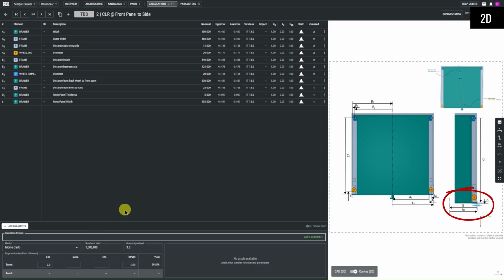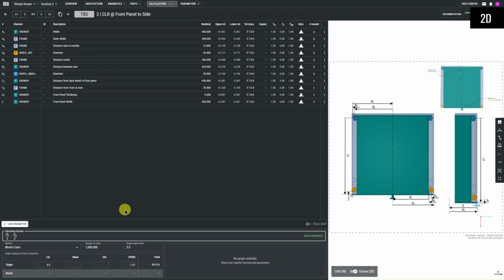First, we add the parameters from the simple 1D stack, A2 subtracted by E. Then add the clearance from each of the wheels, which both overall work in a negative direction for our point of interest. Beware, the result of the parenthesis should therefore be positive. The fourth term is the clearance at the back wheels using all the B parameters. Notice that all terms are divided by 2, as we only need half of the total clearance.